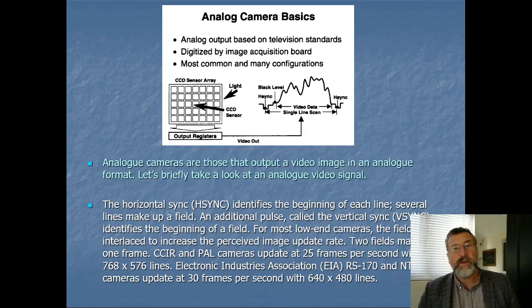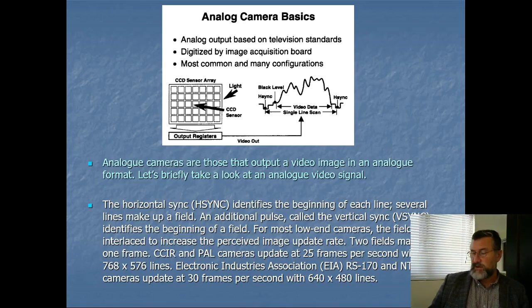Years ago, it used to be a bit complicated, just as a little bit of historical interest. We used to have analog cameras, which is a bit crazy, where we had a CCD producing a digital image, then converted that to an analog TV standard, then had an analog to digital converter in the frame grabber to convert it back. That was a bit crazy because you lost resolution and you got noise, so it wasn't a good idea, really. We used to have TV standards, of course: in the UK it was PAL, in the States NTSC.